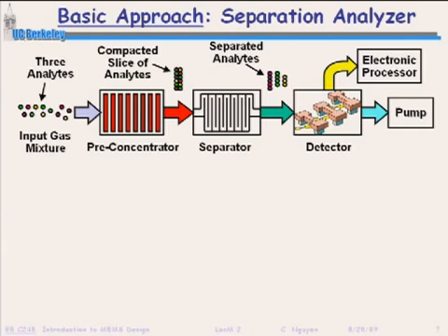All right? Now, the problem is, and this is how the macroscopic ones work too, but the problem with the macroscopic ones is things are slow, right? You looked at that chart back there. They were slow. You couldn't detect very well, and it took too much power. Okay, so here's where miniaturization solves all of those problems. So the pre-concentrator, I just described to you how often they implement these things. You absorb on a polymer, then you shove heat into the thing, right? And then the gas comes out almost immediately when you shove that heat in. Well, you're shoving heat in, that's power. Right? What did we learn from our atomic clock discussion? You make it smaller, you get rid of the power.